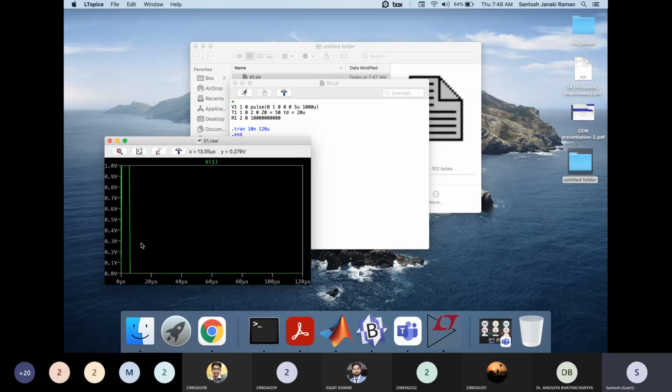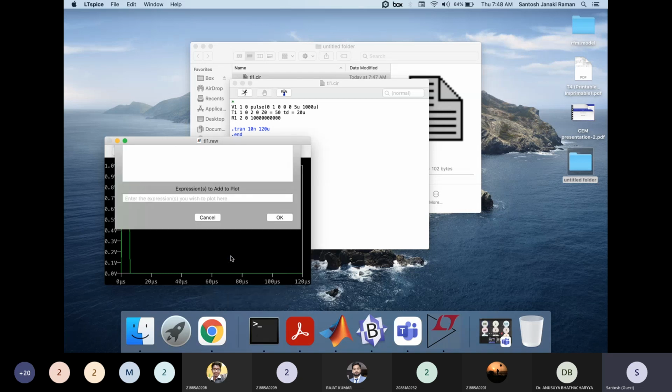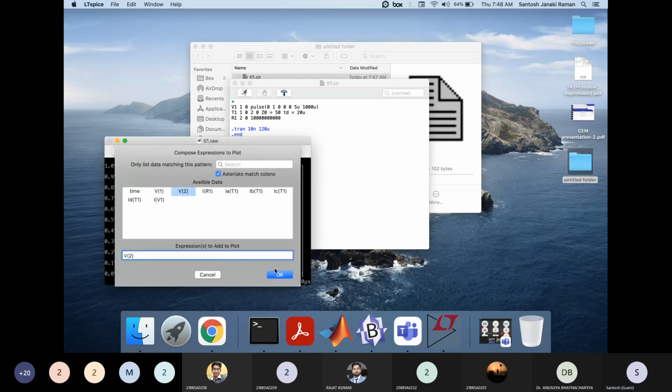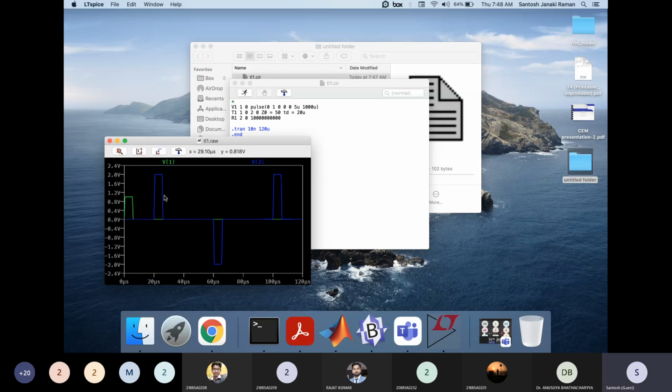So you have the source voltage, a single pulse, and now you see how the load voltage changes at V2. You have a voltage V1 that goes to the load, and it doubles, correct? And now the doubled voltage comes back to the source, but the source is shorted, right?